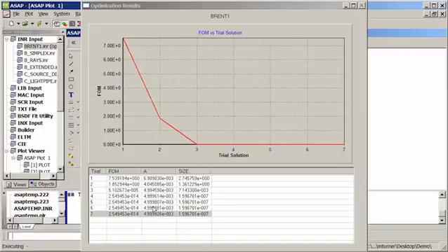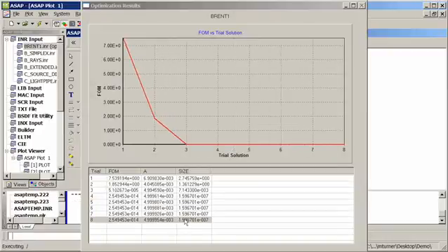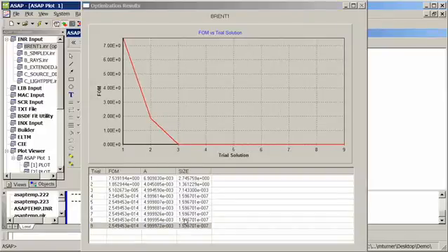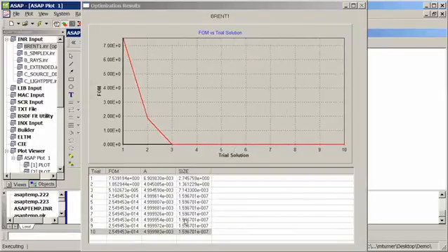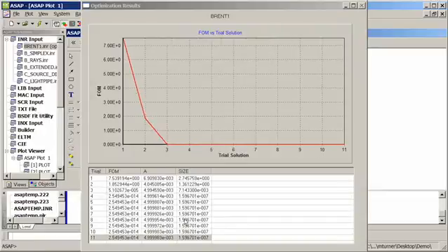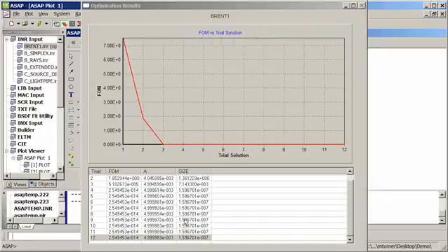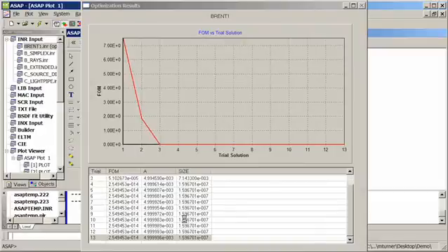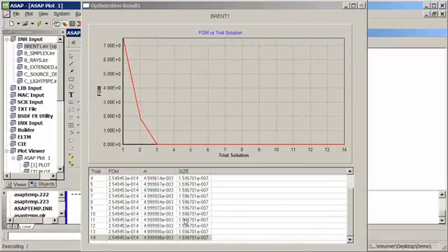And as you can see, in a very small number of cycles, we've probably reached the optimal solution where the RMS spot size is effectively 0. ASAP will iterate through this several cycles, and then when it determines, based on the repeatability of the measurement, that it's not changing, it will cancel out of the measurement.